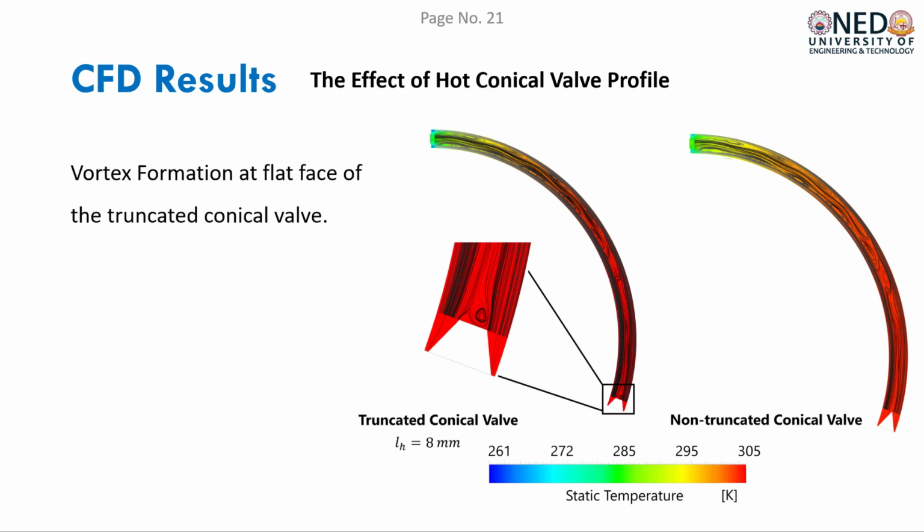The reason for this improvement is due to the vortex formation at flat face of the truncated conical valve, which pushes the separation region a bit further towards the cold orifice region.